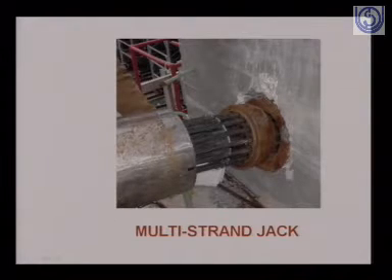This is the jack here, this is the structural member, here it is a duct, and a number of strands you see here. These strands are being stressed using the multi-strand jack. So you can provide the stresses for more than one strand at a time. For that you have to use a multi-strand jack, as is clear from its name.